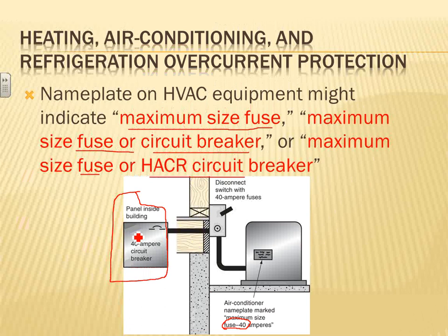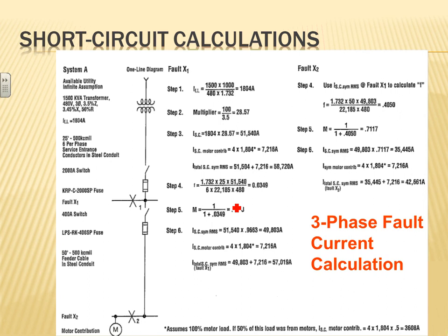You size the circuit breaker here to protect your branch circuit. And then right next to the equipment, you are required to put a disconnect to isolate the system to work on it safely. You stick a fuse rated inside. Instead of a non-fused disconnect, it becomes a fused disconnect rated based on what they want you to do. So the circuit breaker becomes nothing but protecting your conductors.